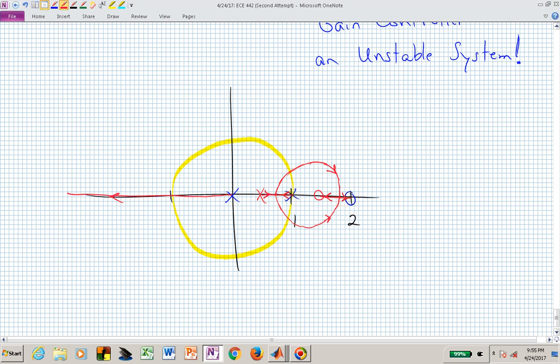What we're hoping then is that we can now crank up the gain to some value less than, let's say, these boxes. And so for a tiny gain for this choice of pole and zero, now we introduced another zero outside the unit circle, and for that, we have stabilized our system by putting a pole inside the unit circle.